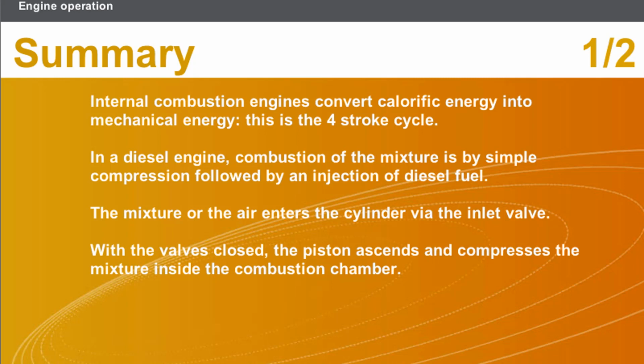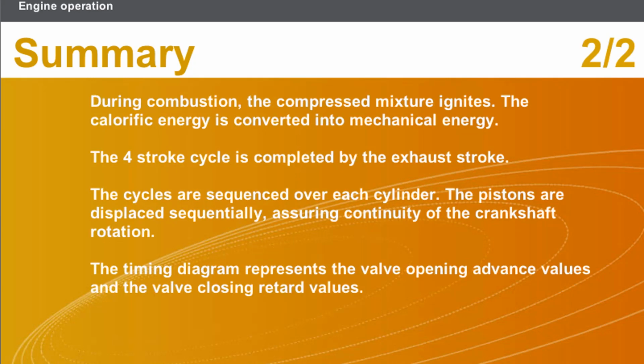closed, the piston ascends and compresses the mixture inside the combustion chamber. During combustion, the compressed mixture ignites. The calorific energy is converted into mechanical energy. The four-stroke cycle is completed by the exhaust stroke. The cycles are sequenced over each cylinder. The pistons are displaced sequentially, assuring continuity of the crankshaft rotation. The timing diagram represents the valve opening advance values and the valve closing retard values.